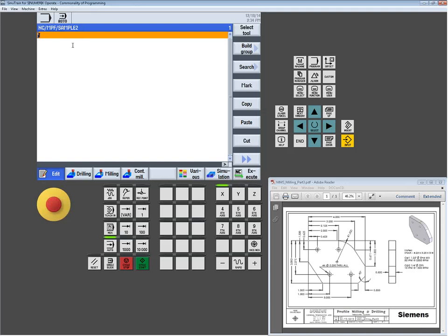So when you're writing a G-code, very traditional, you do like I say, start, header style, start. So this would be, maybe I want to tell the machine I'm G90, I'm in an absolute mode. G17, that's my orientation of my tool. G54 is my work coordinate. G70 or G700, both in our world stipulating inch mode. So you can start to build up. A lot of the stuff you're seeing here was all taken care of in that first header screen of the program. So that's fundamentally one of the big differences, because you don't have a header here. So you'll have to break out.